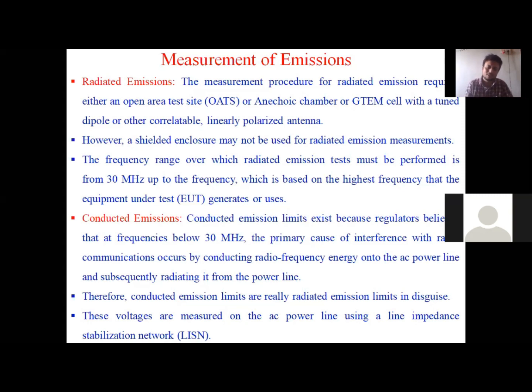And please remember, this emission does not exist away from the conductor. This emission is existing very close to the conductor, because this emission is generated by a conducting wire whose length is much smaller than wavelength. So they are not good radiators. These are cables, transmission lines. So this emission will be very less. So this emission has to be measured in near field.